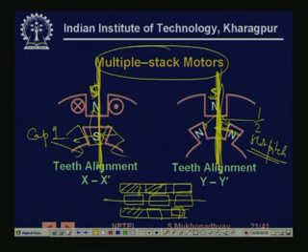from each other. So, the rotor teeth on the first rotor stack and the rotor teeth on the second rotor stack are slightly offset. So, when you excite the first stack, the teeth get aligned with the first set of stator coils, then you switch it off, or if you are doing half stepping you can also keep them on. After you have excited this stack, now you excite the other stack. Now, since the teeth are slightly offset, they will further rotate and get aligned, then you excite the other stack.